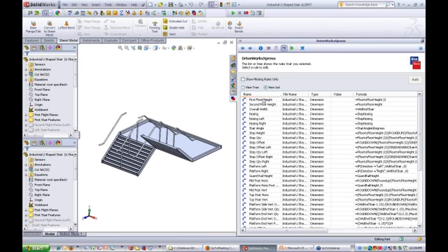So for example, the first floor height dimension, now that's a dimension that's been captured in SolidWorks and given a name of first floor height. That will be equivalent to the floor-to-floor height we entered divided by 2. Second floor height will be equivalent to the floor-to-floor height that we enter, and so on, as you can see down through each of those rows.